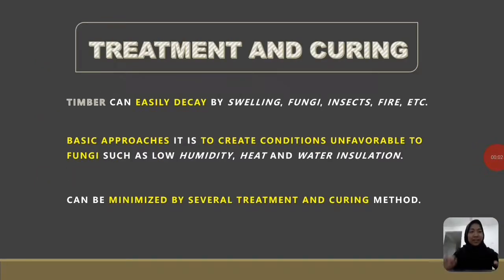Treatment and curing. As we all know, timber can easily decay by swelling, fungi, insects, fire, etc. The basic approach is to create conditions unfavorable to fungi, such as low humidity, heat, and water insulation.